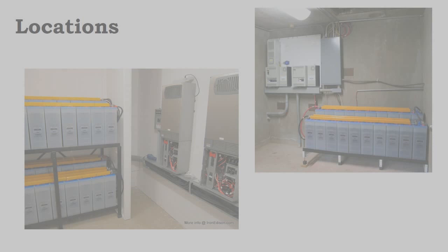And so we look in these rooms, and the question is which of these rooms is compliant or not. These both would be considered damp locations. There's actually a few points about this array that are not compliant. The first is the depth. The batteries stick out more than 6 inches from the service panel. Now, we do have 6.5 feet of headroom electrical space, and we do have the width of the equipment or 30 inches of access on this side, aside from that depth violation.